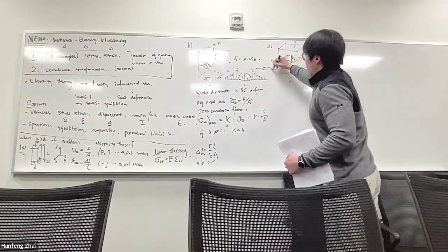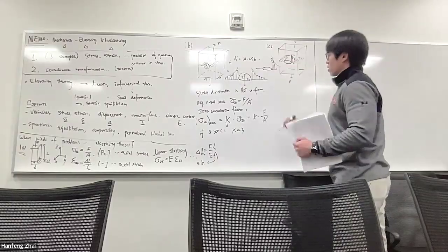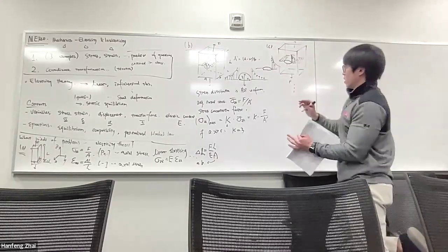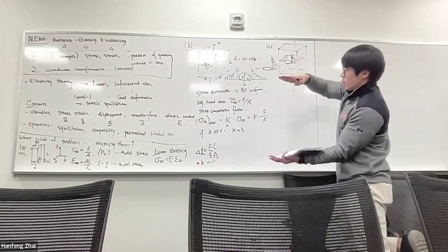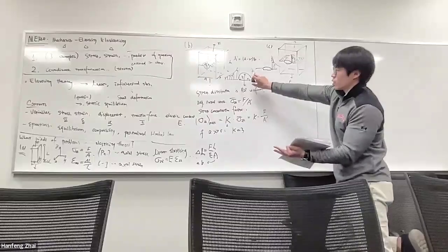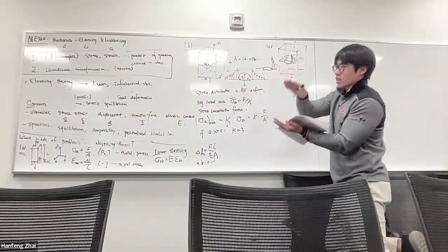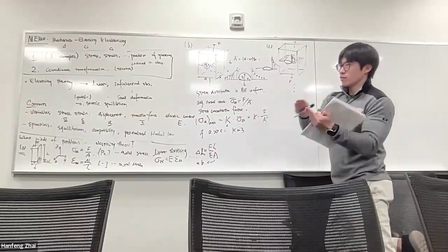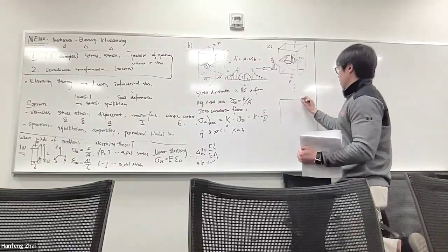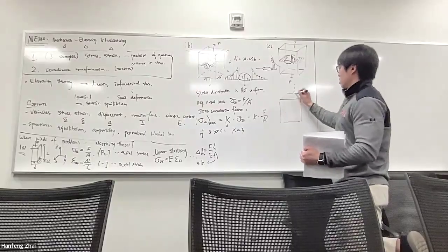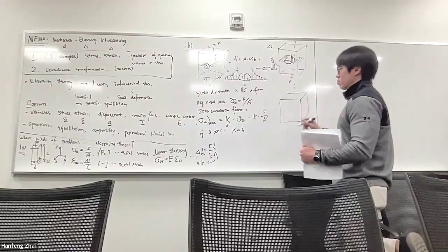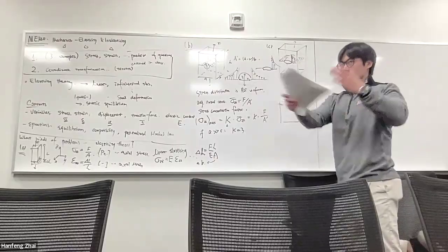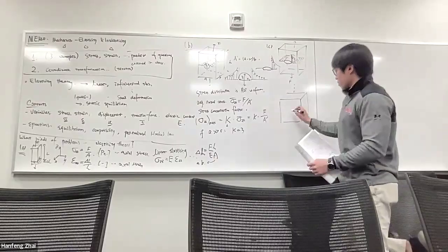Compared to this, and you will learn how to derive the stress concentration factor. Now, what if we extend this example and turn this hole into extremely flat? If you shorten beta, we call it flattening the hole. If you turn this hole extremely flat, where beta goes to 0, then it becomes a defect or crack, which is also an important problem in different engineering fields among your research backgrounds.